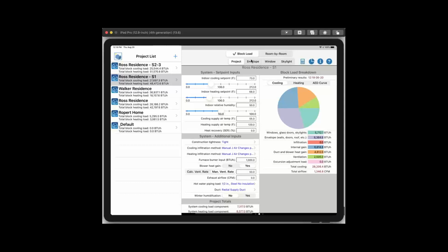If you're in Denver, which is 5,000 feet above sea level, that 1.1 becomes a lot less, like 0.8 or 0.9. So that also affects your airflow. The same house in Denver will have a different airflow than a house at sea level, say in San Francisco, assuming the outside air temperatures are the same.